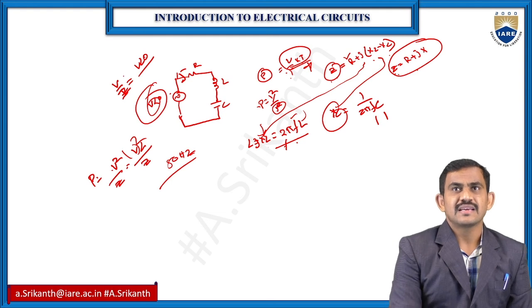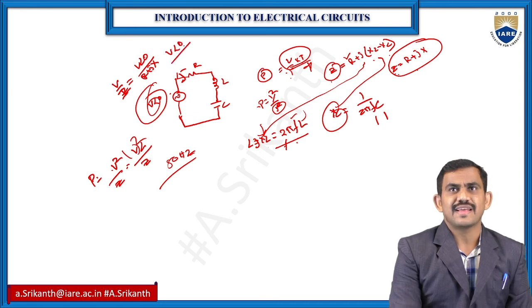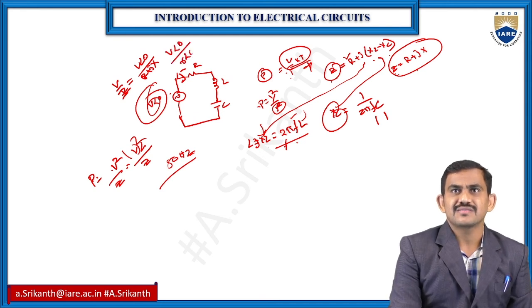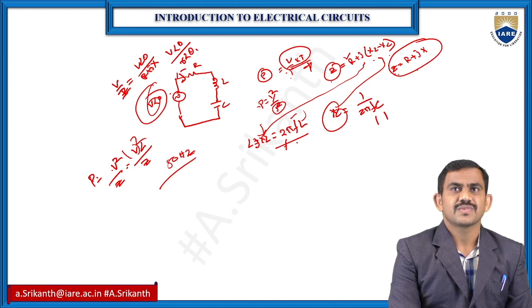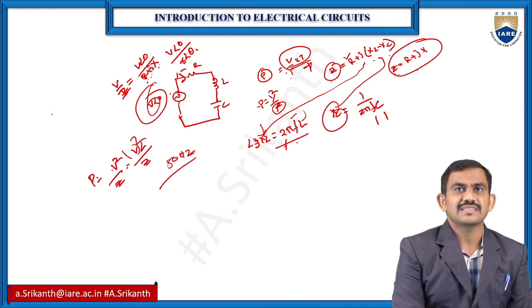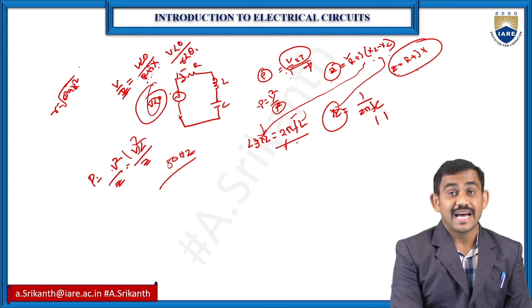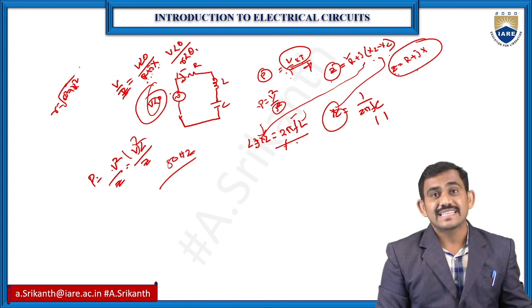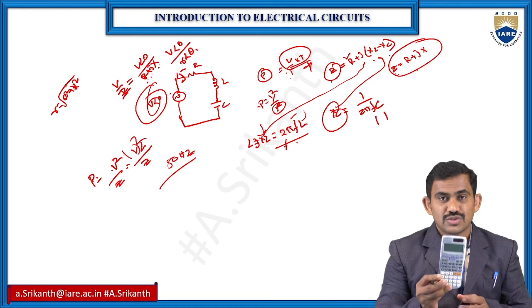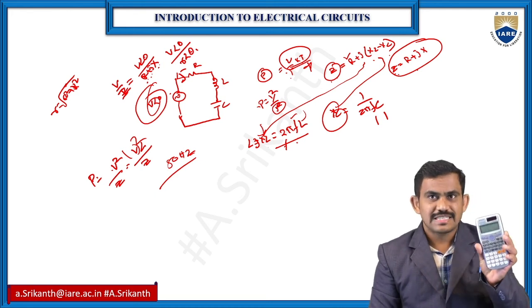Impedance is in rectangular form, R plus jX. So you can convert it into V angle 0 as well as Z angle with some theta. For R plus jX, we convert into the magnitude, which is nothing but the root of R squared plus X squared. Otherwise you can use the calculator, which has steps to find those values.